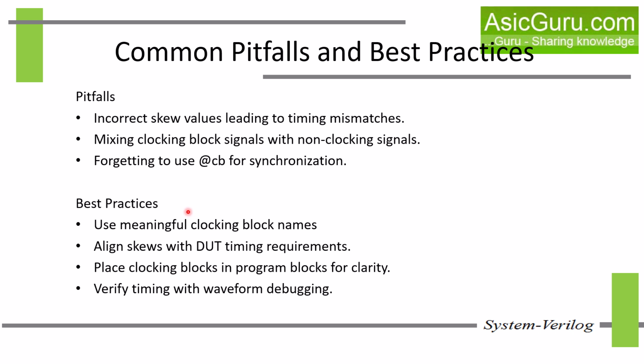Now let's talk about best practices. Always use meaningful names for your clocking blocks and make sure to align your skew values with the DUT timing requirements. It is also a good idea to place your clocking blocks inside program blocks. And finally, always verify your clocking block behavior using waveform debugging. By avoiding these pitfalls and following these best practices, we can write much more robust and maintainable testbenches in SystemVerilog.